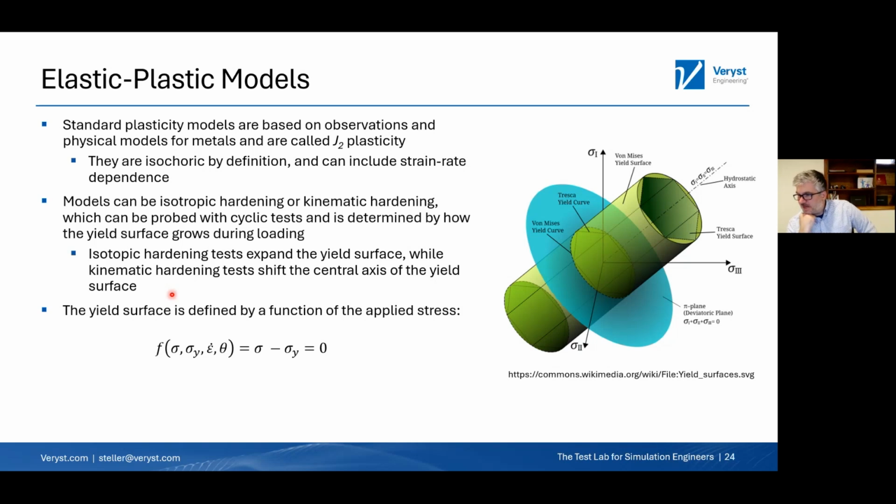There's another question here. It says, for elastomers operating at temperatures ranging from 100 C down to 5 C, how should temperature effects be captured in a hyperelastic model? There are a couple of ways to do that in Ansys. One is to use time-temperature superposition principles, where you have parameters for the WLF or the Arrhenius relationship. That can be a little more obtuse or difficult to do. The other thing you can do is calibrate a material model at the different temperatures that you have test data at, and then tell Ansys that that's what the temperature dependence is, and it will linearly interpolate in between there.